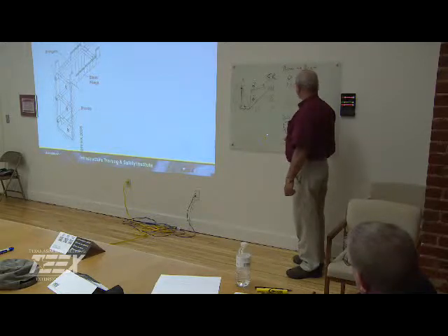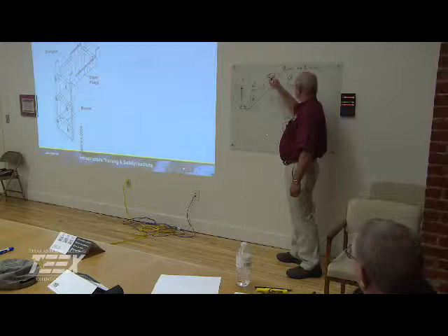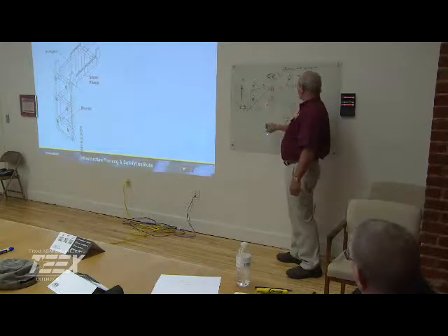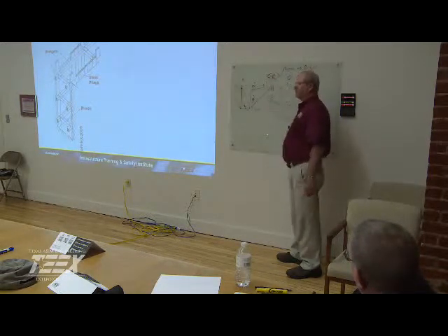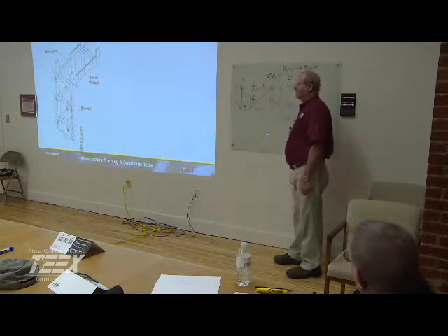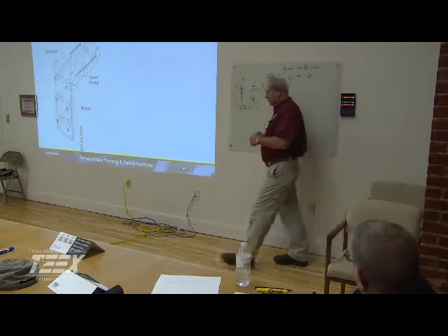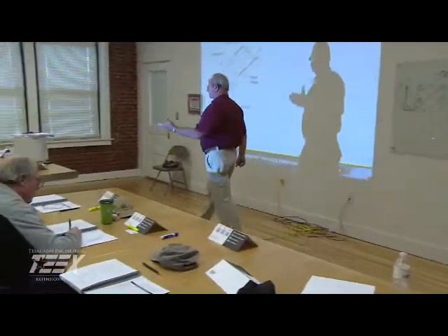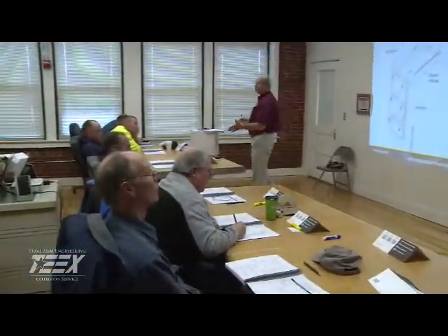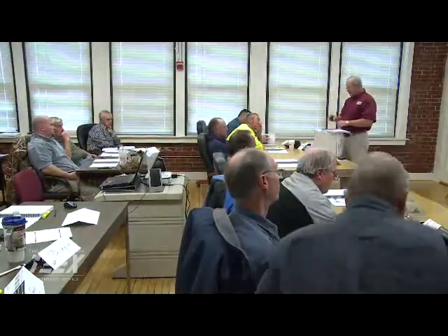Okay? And now, in all previously excavated areas, I don't care if it was stable rock A or B, it will always be a C after that. Okay? So if you're excavating in any area that's been previously excavated, it'll always be a Class C after that. And the reason is the soil right next to it could be a trench. You never lay water or wastewater lines in the same trench.